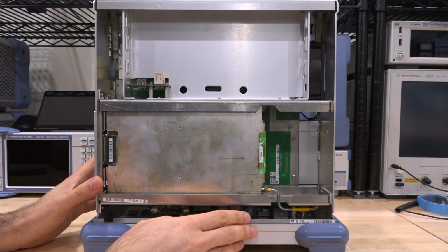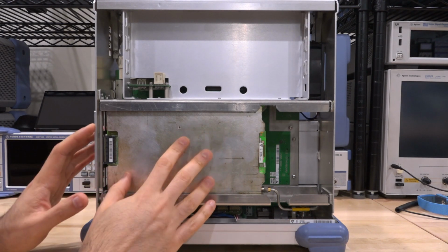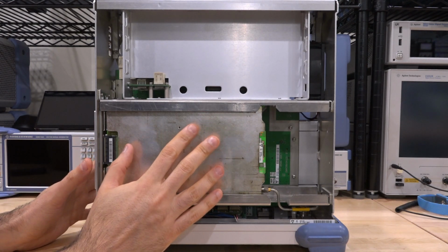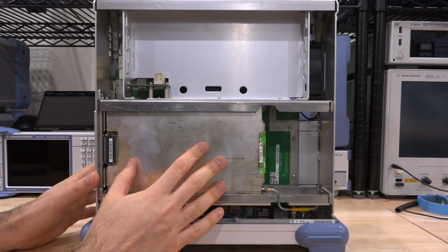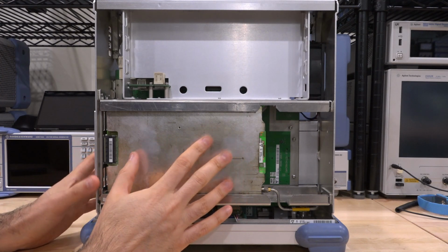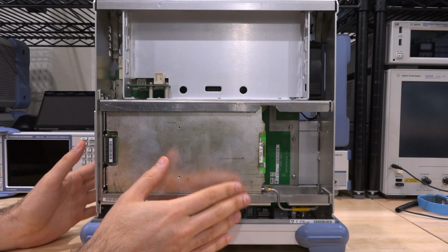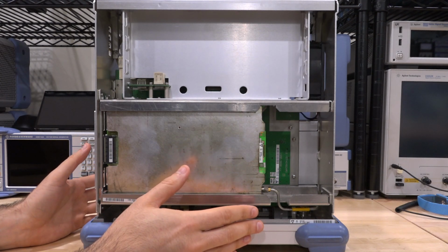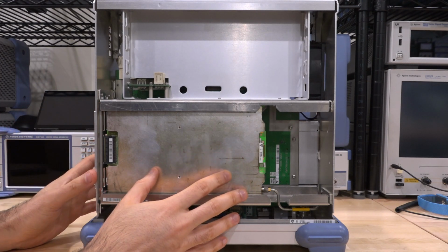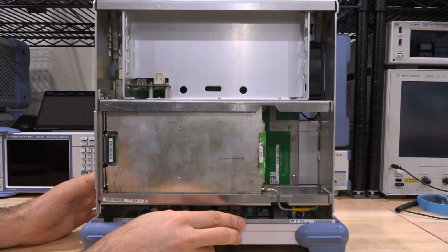A little bit closer look reveals that the RF connector, which is coming over here, goes into this board. And the only other connection to this board is this ribbon cable in the back. So this is the entire spectrum analyzer from the RF point of view. This is common for entry-level spectrum analyzer architectures where everything is on a single board. Rohde & Schwarz is quite good at that, but this will never have the performance, of course, of a dedicated LO, dedicated IF, RF front-end with various frequencies, filters and so on. Of course, Rohde & Schwarz does that with their higher-end spectrum analyzers, but this is probably an entry-level one. But everything is in here, so we should be able to take a close look at it.